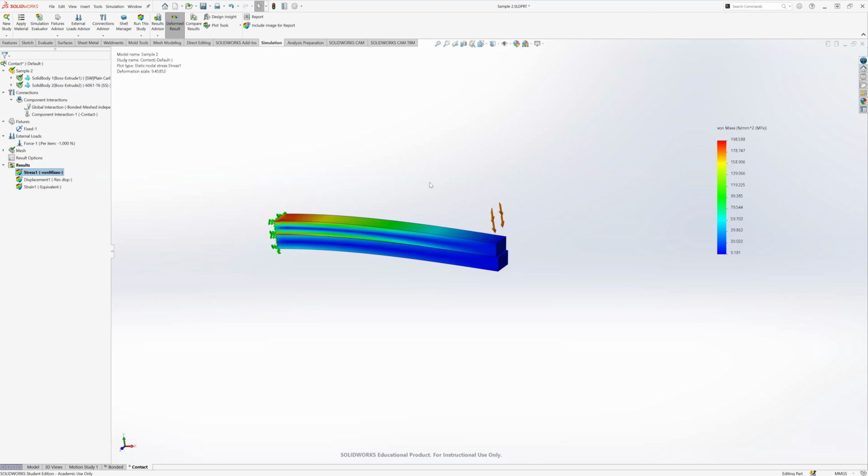One thing you can do is a component interaction between them. Let's say you call them bonded, and then you go in with a local interaction and do, let's say, a contact. Again, it's going to go from the global level to the component level to the local level. So the more in depth you are into the thing, the more that interaction is going to take precedence. So local is going to take precedence over a component. A component is going to take precedence over a global.